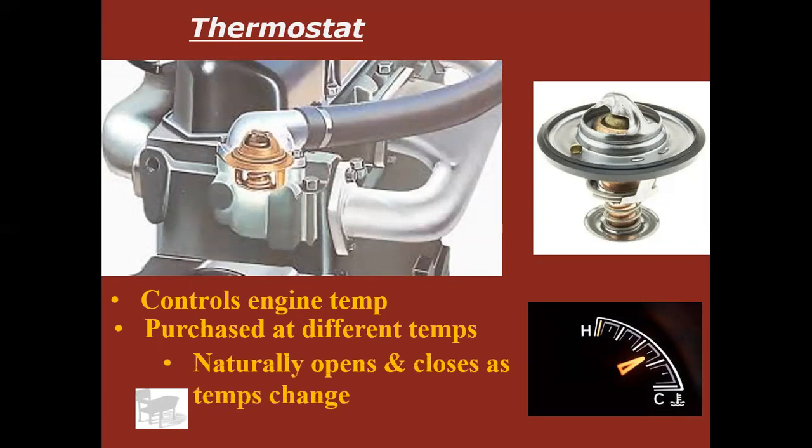And we talked about it naturally opens and closes as the temperature changes. This doesn't require any outside power. There are different designs, but there's essentially a spring that, as it cools off or heats up, depending on how it's set up, gets weaker, and then another force overcomes that and opens or closes it.